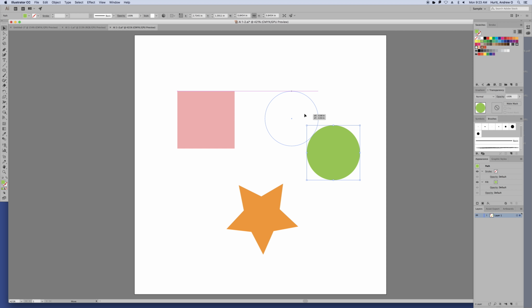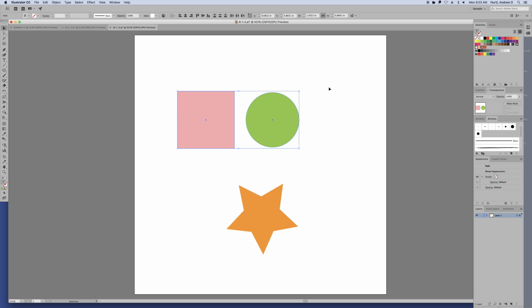So now these two objects, using your smart guides, will allow you to line these up vertically at their centers, right? You can also, if you go up a touch, or I'll move it down, align them at the center, or you can align the tops, you can align the bottom, etc., etc. You can shift select, or what I tend to do a lot is drag and select. I'll just start in an empty space and drag over the 2 objects that I want to select.